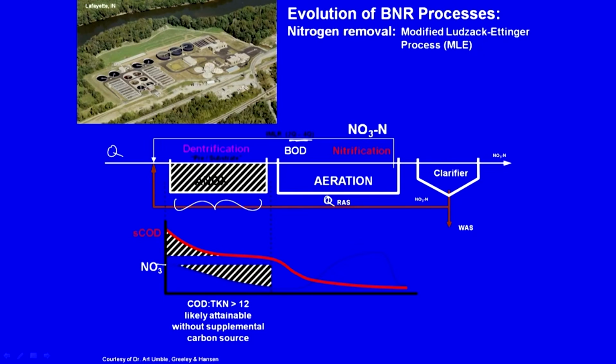Why is that? There is more nitrate. So, efficient carbon utilization and higher nitrogen removal, and during aeration you have further removal of the COD or BOD, and during aeration you have nitrate being increased, but again because it is being recycled, let us say they are in effect saying that this is what it will look like. So, in general net you will have a greater nitrate removal.